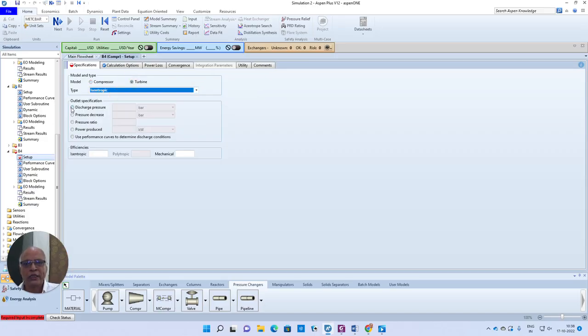isentropic. What is the discharge pressure? As you know, the lower the pressure, the higher would be the power output. But one of the problems that we normally encounter when you expand gases in a turbine is there is a possibility for condensation of vapor. For example, water vapor might get condensed. Yes, small droplets of water are not permissible in the case of a turbine because